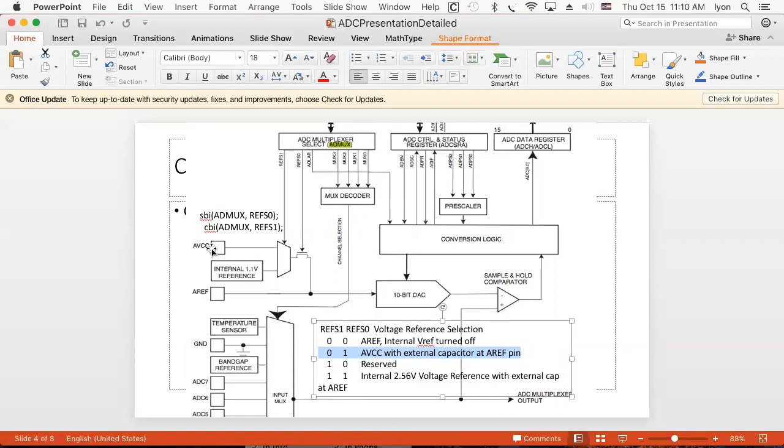Now, put a nice external capacitor in there, and that's going to keep the voltage up somewhat. That's why they're asking for an external capacitor, because they figure if there are fluctuations in the line, they shouldn't propagate to the DAC. So if we're not using an external capacitor, and we're not, then we are in the "we don't care, it's good enough for us" camp. And that's all right if all you want to do is digitize an analog signal.